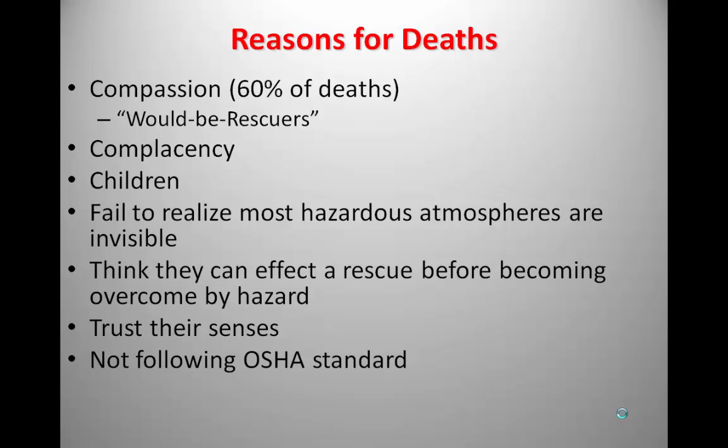The other issue or reason people die is they fail to realize most hazardous atmospheres are invisible. They just say, well, I can't see anything bad, so there's nothing bad in there. Or they think they can effect the rescue before becoming overcome by the hazard. There's another case study in the book that refers to a person trying to rescue a family member. They were down in a manure pit in one of the barns, and a person tried to effect the rescue by holding their breath, going down into this manure pit.